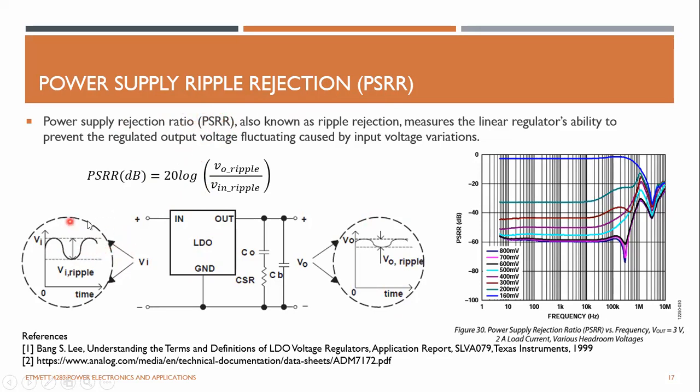When you build efficient power converters, you might have multiple voltage regulation stages. At the post regulation, which is where you connect your load, by connecting an LDO regulator you can get rid of any noise coming from the upstream voltage regulators like switch mode power supplies, and keep a very nice and clean output supply.